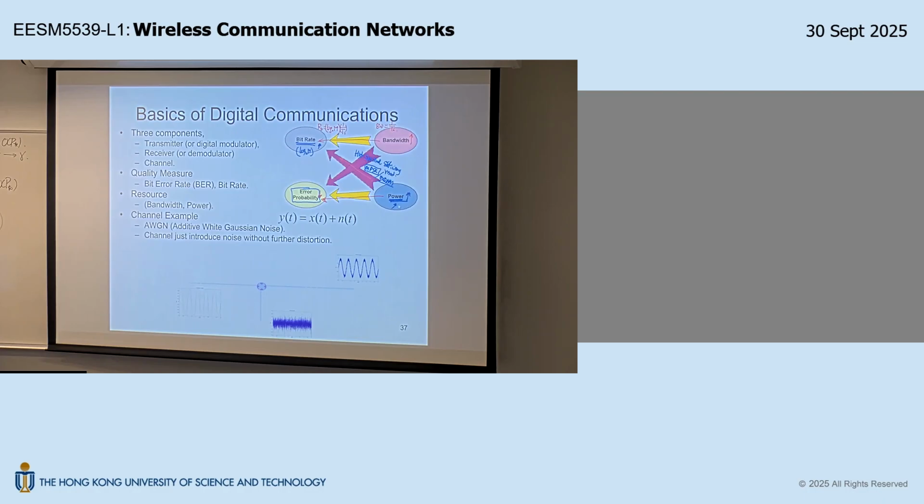Anyway, just keep in mind, this high-level modulation requires high signal-to-noise ratio. So usually, for extremely large M, you need to make sure that your system is more like a noise limited system than an interference limited system. For an interference limited system, usually the M cannot be too large. Otherwise, you never get a chance to operate.